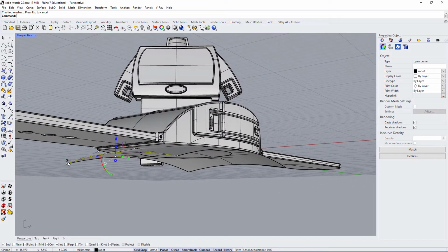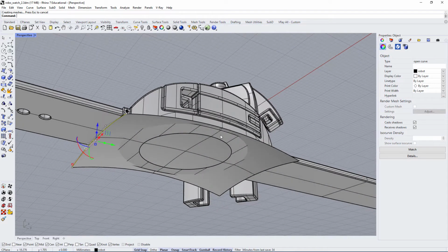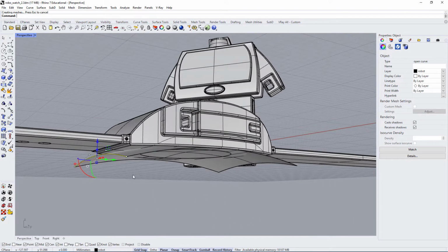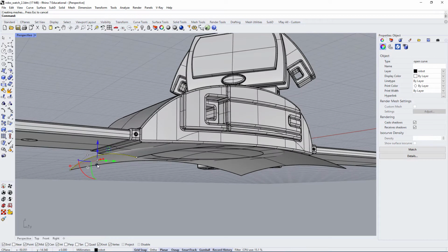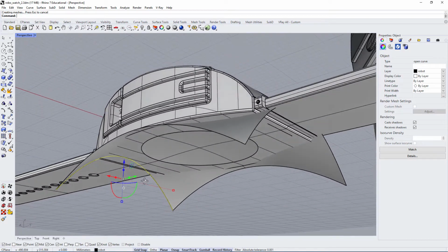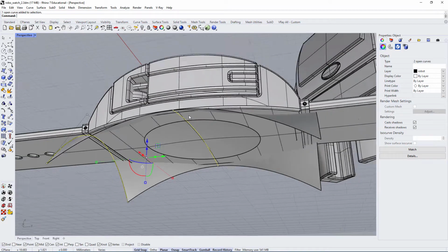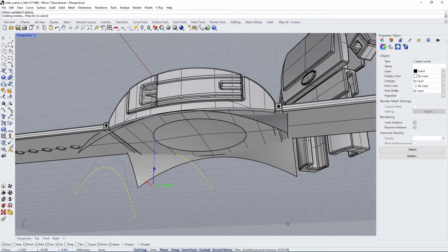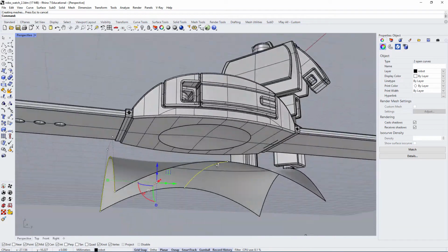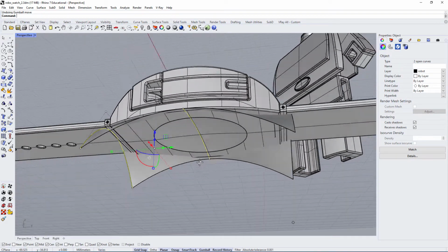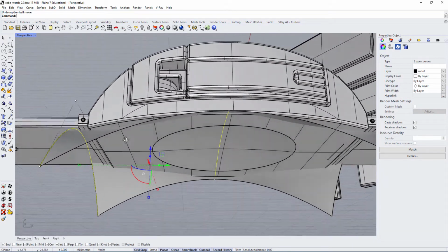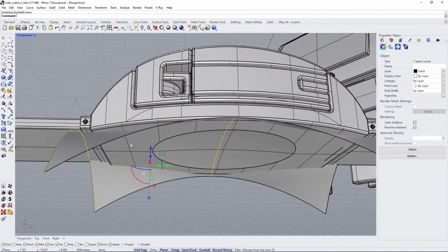And yes, the profile curve is the same 3 times. So it's the same at one edge, at the center line, and at the other edge. But we can change that by scaling the object. So we can scale this object here, and we can get some really complex curvature. If I select the center curve, you can see what this surface looks like, and it's actually very, very complex. So that's one very quick way to add some surface complexity to your object.